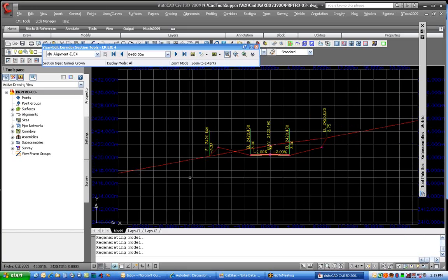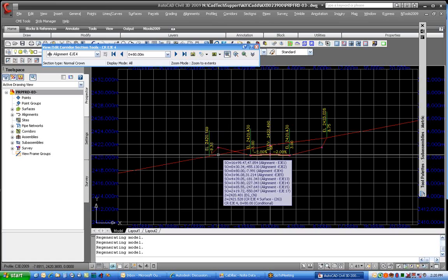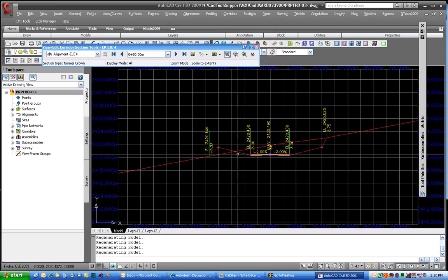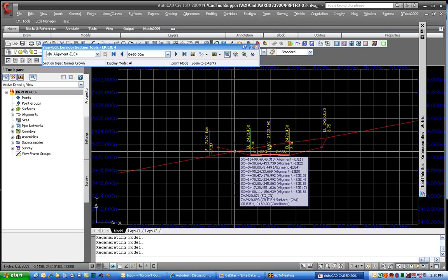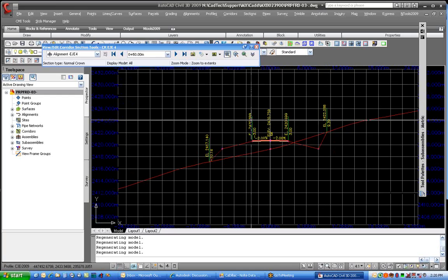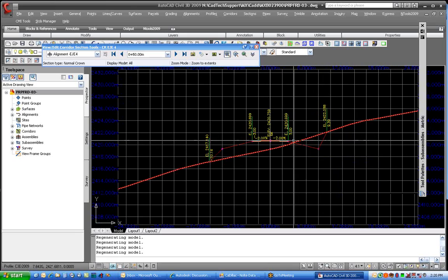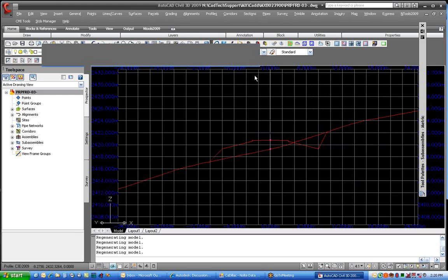Okay. Problem with that is I wasn't really happy with this because it's testing the depth here, but really where I think we need to be testing the depth is at 5 foot out. Is it in cut or fill 5 foot out? Because it doesn't make sense where I could probably go at some grade through here and just connect, maybe daylight to that point there. I don't want to create this little mound here, or back in situations where I cross over. Here I'm building this big ditch in the back, and we really don't want that. We really want to have a 25% slope going into here. All right, so let me show you a variation that I did on this.